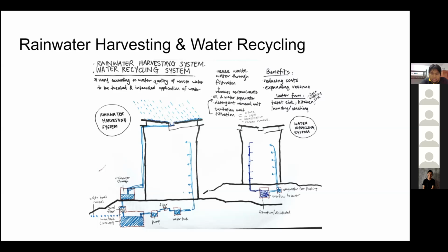dispersed into the soil. And from there, can you also look into not just having polypropylene tanks, but perhaps something a bit more interesting. For example, you can have a reinforced concrete tank where the water goes in, and the tank has two separated compartments, a smaller one to receive water, where it's filtered slightly, and then it goes to a bigger one. In the bigger one you can put plants, you can put fish in there. You can do a bit of aquaculture. There's a lot of things that can be done if you stretch it a bit. Okay, sure. We'll look into that.